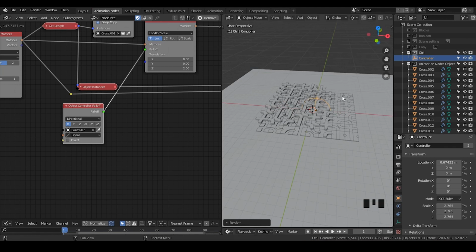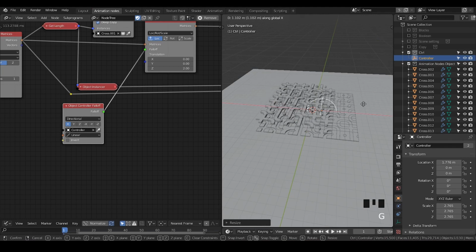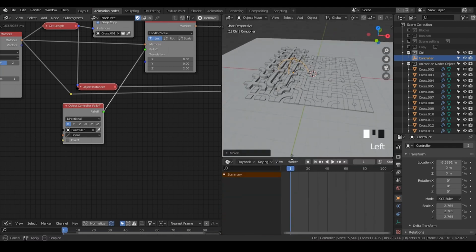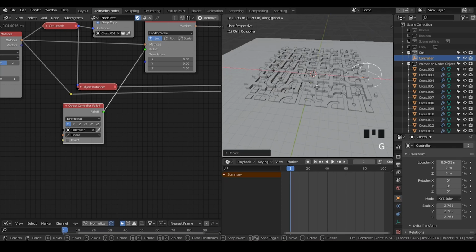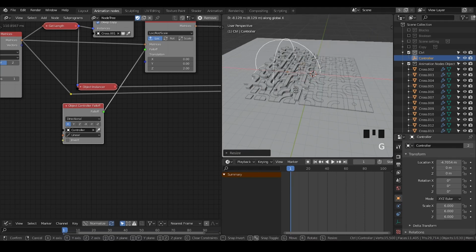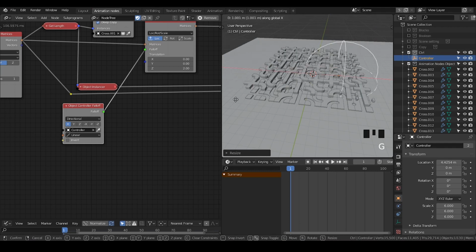I'm going to change the type to directional, change the X, and you can see by changing its X, now they are having different behavior. If you increase the size, it means you're increasing the softness of our fall, which is just like spacing the keyframes farther apart so that you have a more easy movement. This is basically how it works. You can even increase its size. I think usually 6 is good enough in this case. It depends on how you would like to animate that, but this is it.